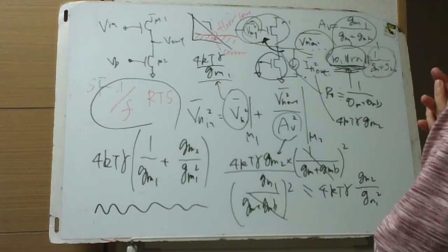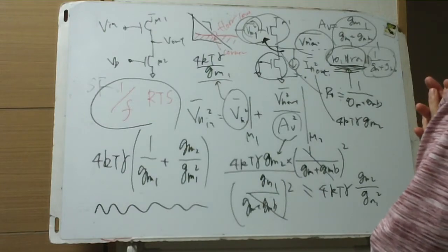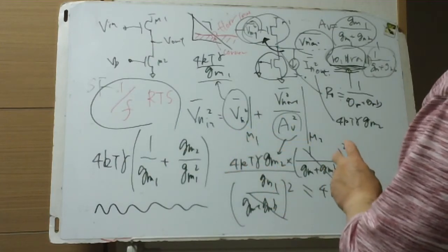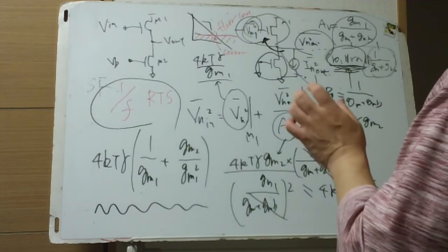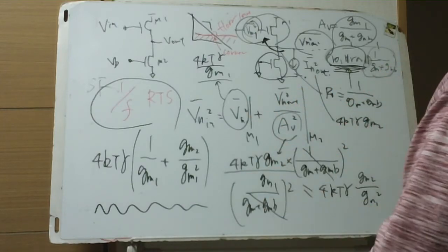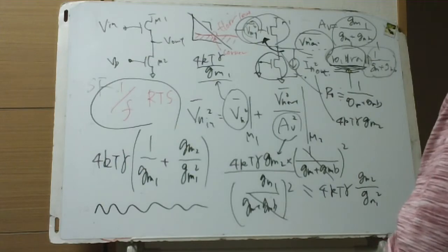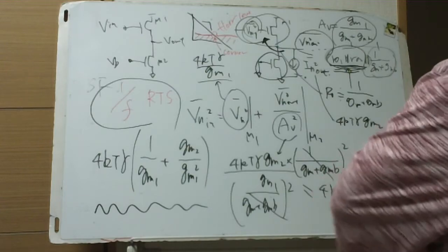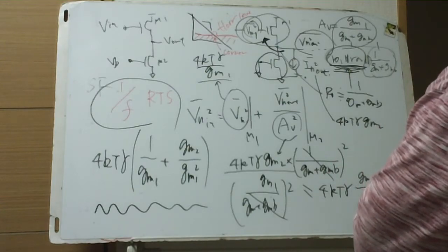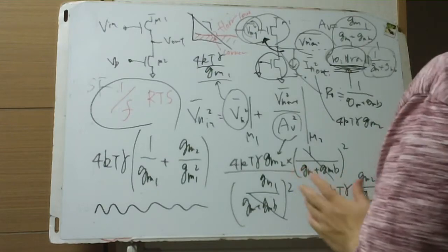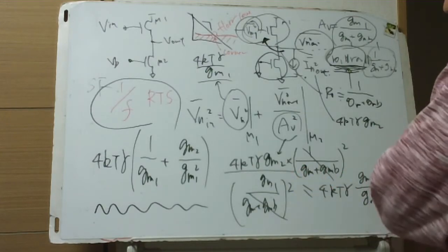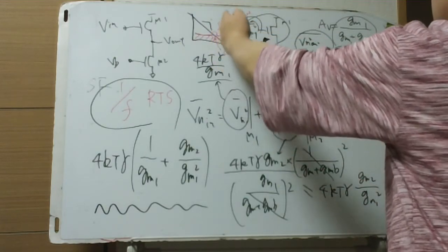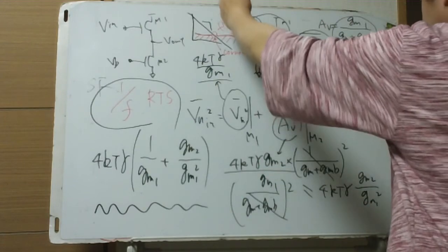The measure is, in some cases, CDS, correlated double sampling, or in other cases, the chopper amplifier technique. Mainly these two are very famous, and using these techniques we can neglect 1/f noise when adequately designed.